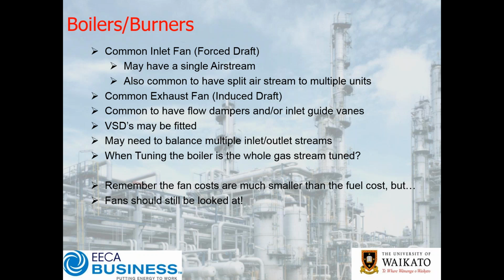So very important in terms of solid fuel boilers to get good airflow distribution. Gas boilers generally, by their very nature of their design in terms of the burner heads and all the rest of it, being an integrated unit, should generally be pretty good and not such an issue. But on your solid fuel boiler, if you have one, very, very important to get your airflow distribution across your grate just right. When you've got common exhaust across multiple boilers, need to make sure that you get that right, that you don't cause issues with systems coming on and off. Very important to get your flow dampers or guide vanes in the right spot. If you're using VSDs, making sure that you're using them correctly.